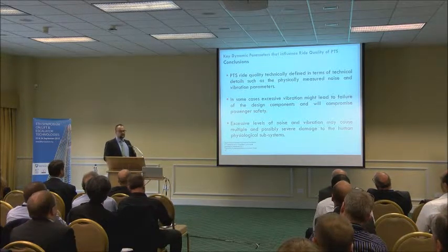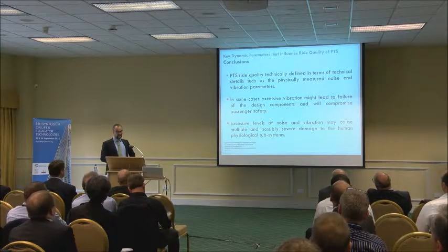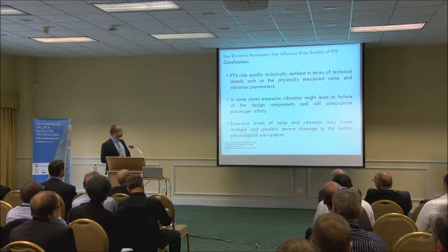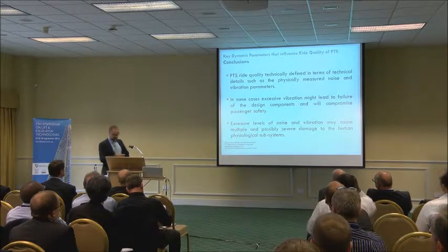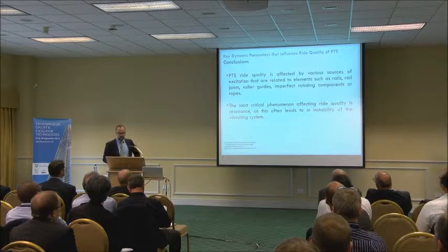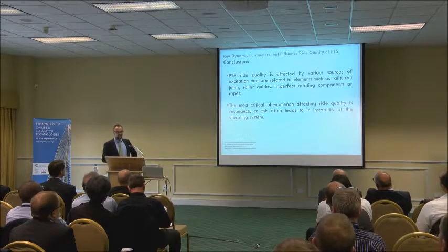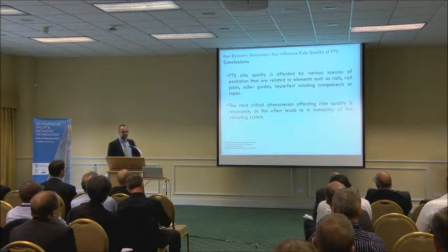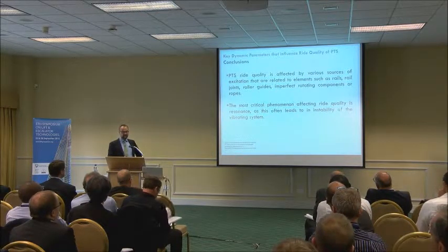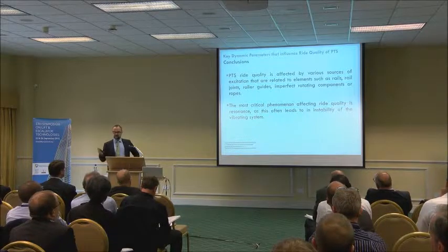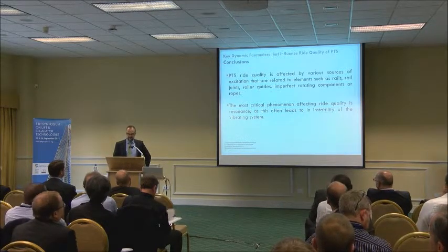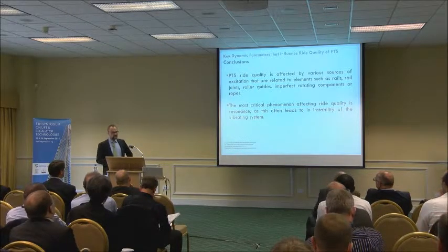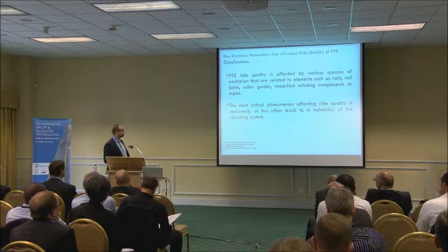PTS ride quality is affected by various sources of excitation, which are related to elements such as rails, rail joints, roller guides, or imperfect rotating components or ropes. And the most critical phenomenon affecting ride quality, and some of you are experienced in this as well, is resonance, as this often leads to instability of the vibrating system.